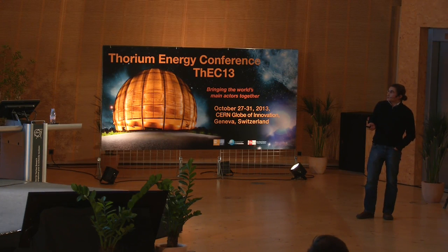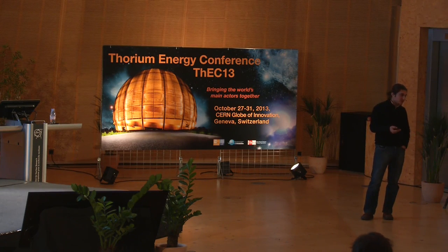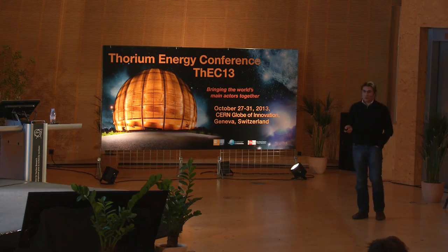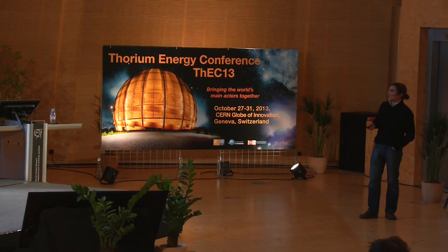and to do it very accurately. To study this, we developed some models of the cavity and of the feedback system. This model enabled us to understand what kind of feedback system we will use, and we are developing it. At the same time, the simulation and the retuning set points of the cavity were determined by beam dynamics simulations. These beam dynamics simulations also enabled us to dimension how much RF spare power we need for the amplifiers, which is around 60 or 70% margin compared to the normal operation of the LINAC.